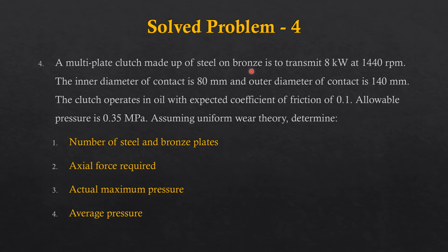All right, so why is this difference here? Because both the surfaces are supposed to be in friction, right? Therefore the coefficient of friction of the surfaces is very important, right? So that is the reason why we have different sets of materials or liners on the disc.